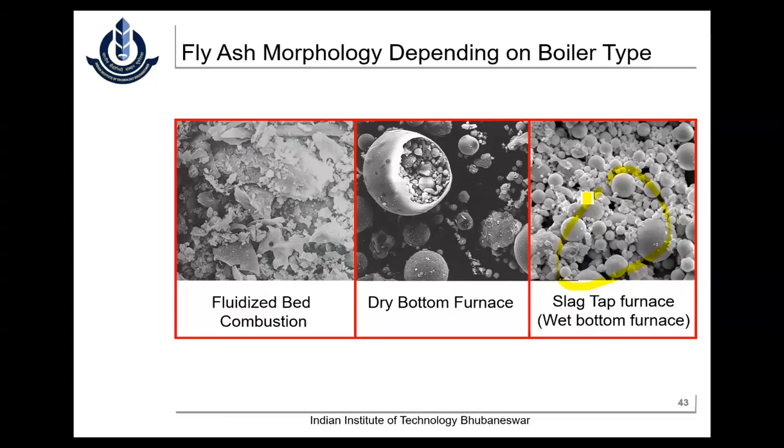Yes, without any hesitation, because of the particle shape. The particle shape gives a matching, wonderful performance, because for self-compacting concrete the prerequisite is only at the fresh state. It should be flowable, it should meet all the self-compacting requirements, and fly ash really plays a wonderful role in that. Because of the ball-bearing effects and all, it is really going to play a wonderful role. Without any hesitation, we have used it in many projects where I gave the mix designs.